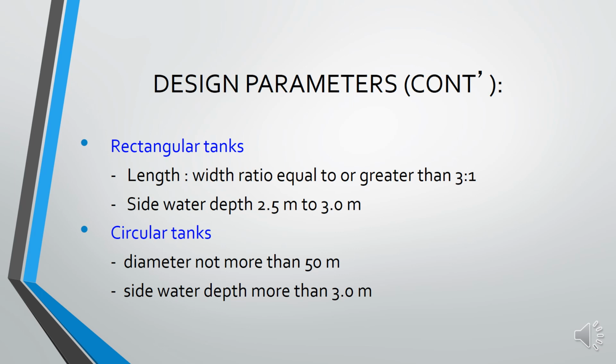So the base of the tank, the floor of the tank, has a slope from the side to the center. So the settled solids will move by gravity, by gradient, to the center to be collected to the sludge disposal or sludge treatment.